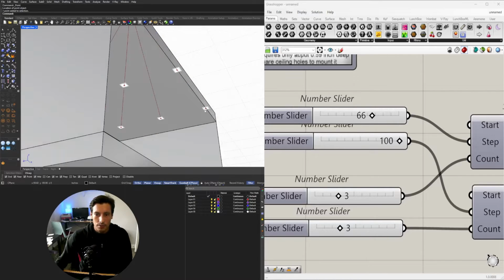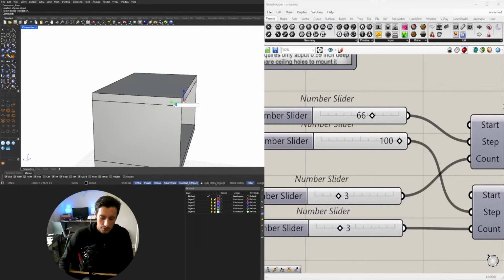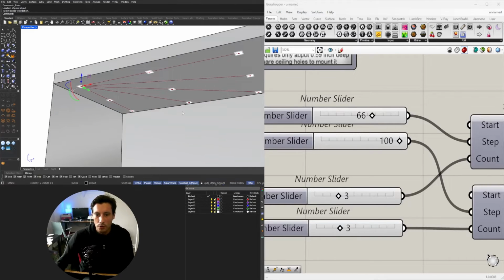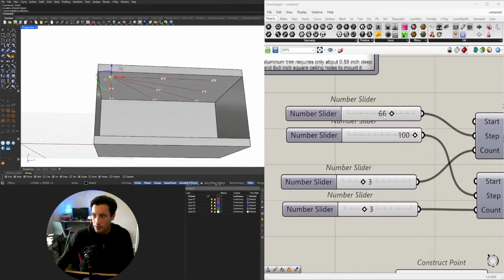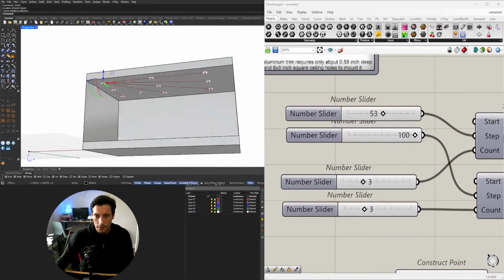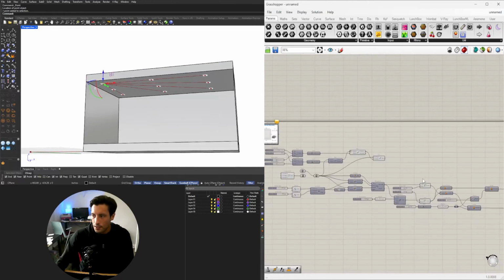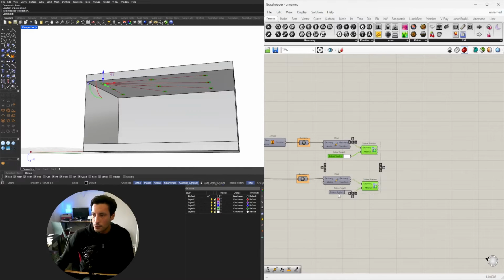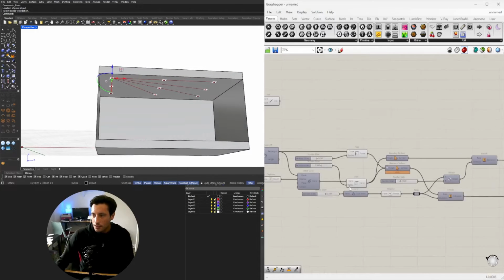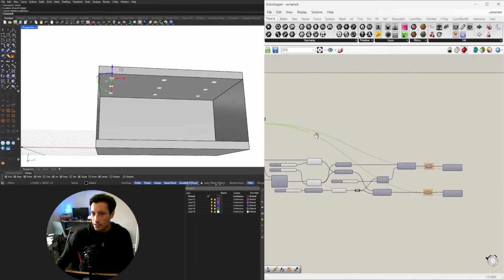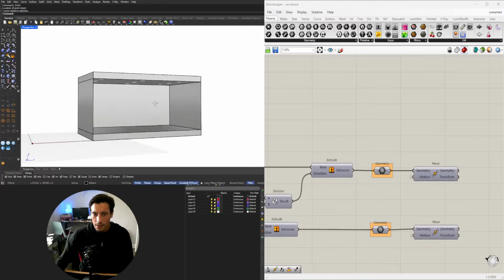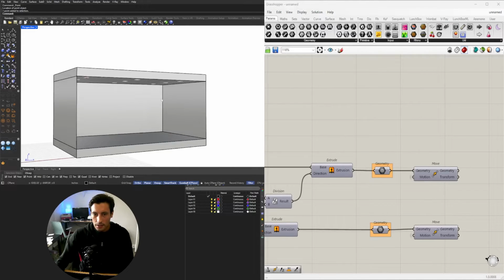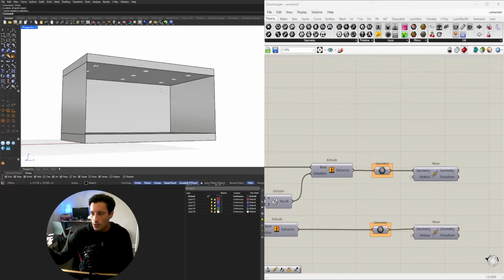And obviously this one is right up to the wall, so we can go here, let's say another 2 feet. Just make sure that we're 2 feet from the wall. Now, the thing I want to make sure to do is that it bakes into its own layer. So this way, when you bring it into your project, you can assign an emissive material to your lights, and that should function as a way to bring in light into your projects and using it parametrically.